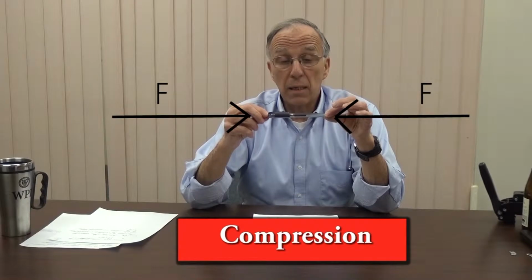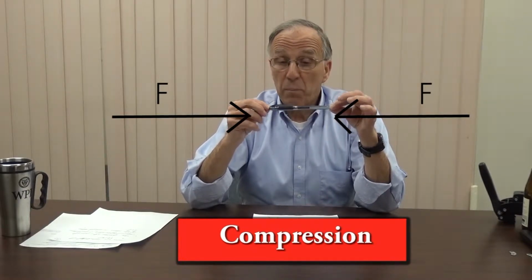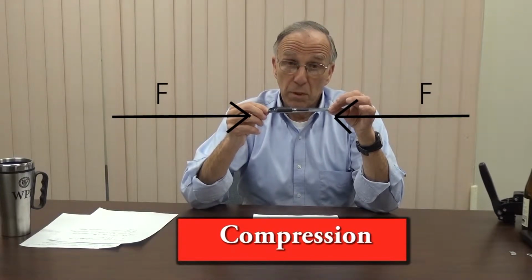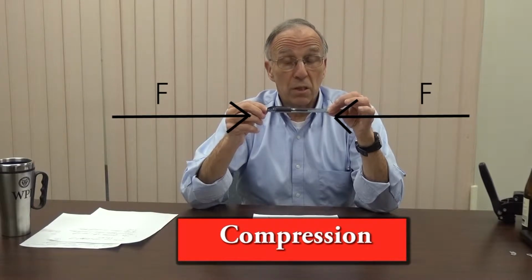The first step in calculating stresses is to draw a correct free body diagram of the object. And so we're going to start out with the simplest type of object that can be held in equilibrium, namely a two-force member. If I take this pen as an example of the member, if I push on the two ends, I'll place the member in compression, and the forces at each end must be equal and opposite in order to satisfy force equilibrium.